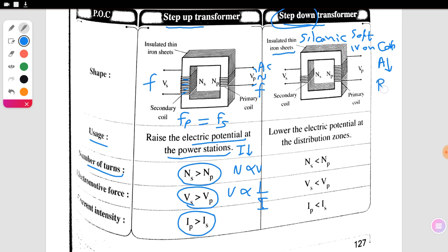This means that resistance is high, and resistivity is directly proportional to the resistance. By increasing resistance, resistivity increases, and the eddy current is inversely proportional to the resistivity. When the resistivity increases, the eddy current decreases, which produces heat energy, to prevent melting the core of the transformer.